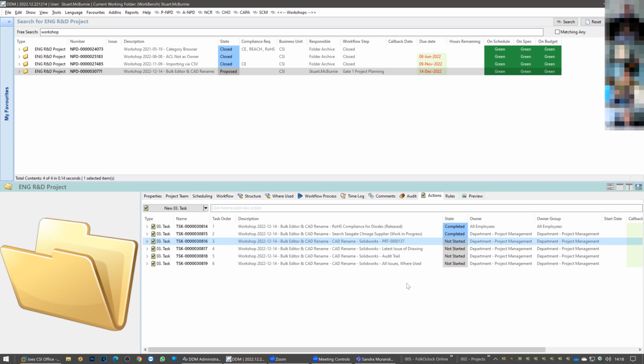The ability to rename CAD files, the easiest way to understand it is if you did this inside Windows, you would break the relationships with any of the parent assemblies or drawings. So it's important if you rename something in CAD that all of the parents are updated. I'm sure everyone's had experience with the need to do this. Of course, the ideal situation is you give something a unique part, assembly or drawing number on day one, and it keeps that number for the whole of its life.